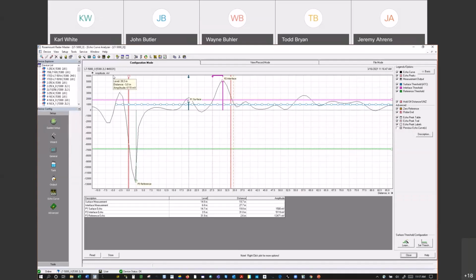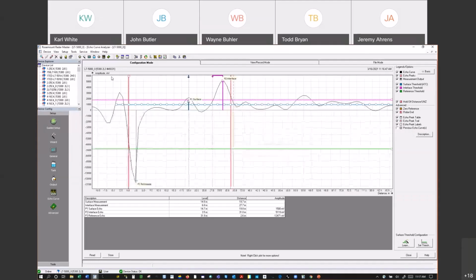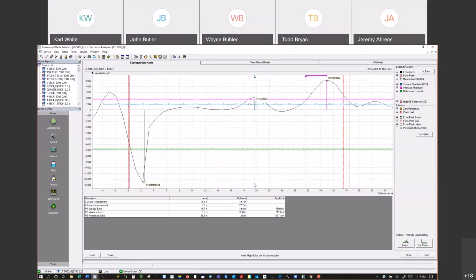What we see a lot of guys in the field do is make them 2-inch, and that's difficult to make a radar work in a 2-inch. If we're in that situation, we'll probably put in our large coax so that we can kind of control how that thing works. But we'd much rather have a larger chamber, a little more surface for the gauge to read.